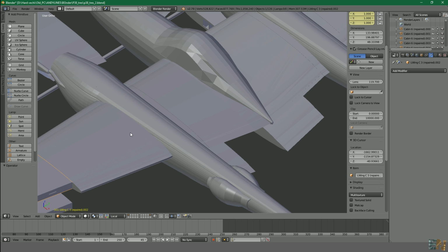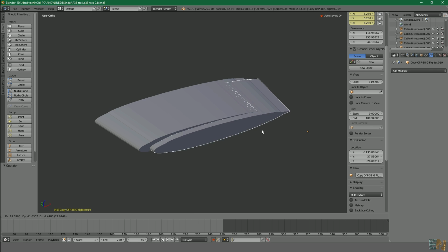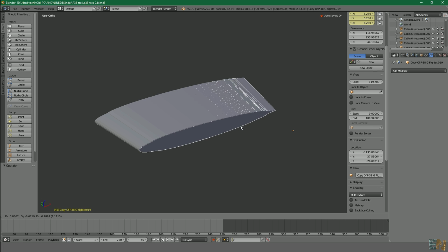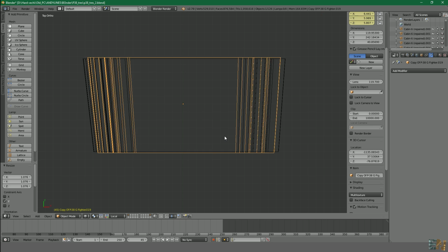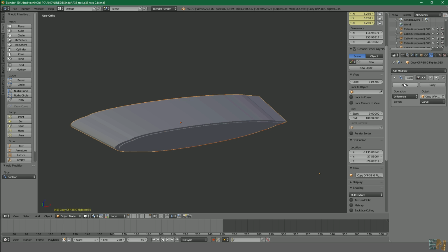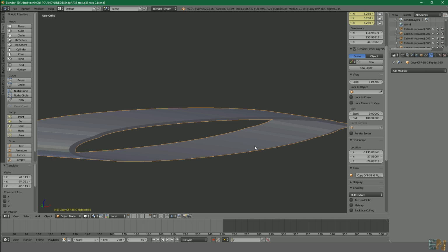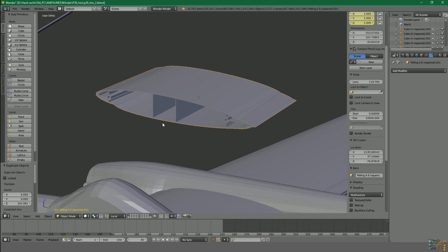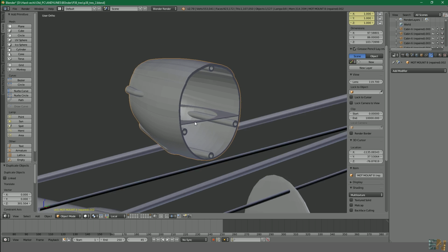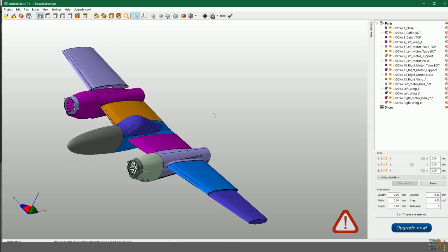That's how I created all the parts for my plane. For example, to make any part just 0.8 mm thick, I create the wing for example. Then I duplicate it and scale it down 0.8 mm all around. I now add a boolean and subtract the small wing from the bigger one, so now I have only the perimeter of exactly 0.8 mm thickness. So I've done the same for the supports inside of the wings, for the holes, the strange shapes and so on, because with booleans you can merge parts together or you could cut some shapes out of other shapes.